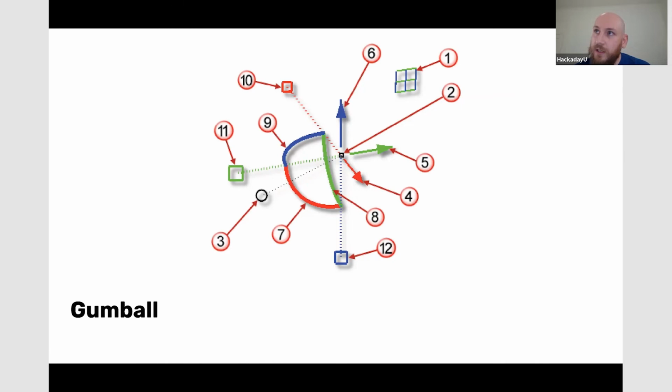In NURBS curves, you usually start with curves and then you mathematically construct those curves very precisely, and then you bring those curves into surfaces and then poly surfaces. So you start at the basics and you build the model through addition. In subdivision, a lot of the time you start with a volume and you deform the volume almost like sculpture, where your volume is clay and you're deforming it.